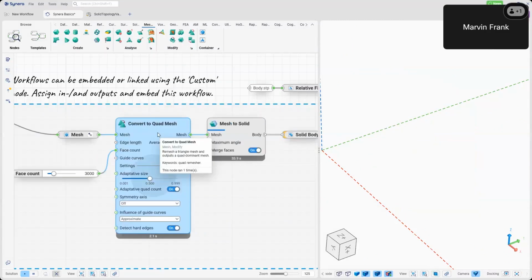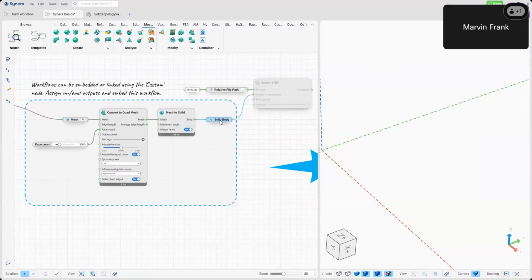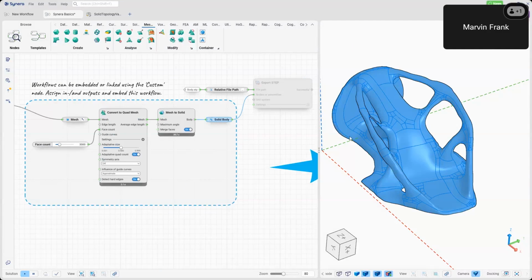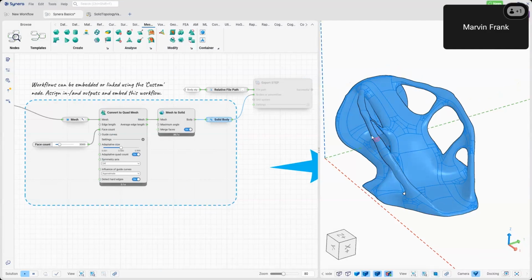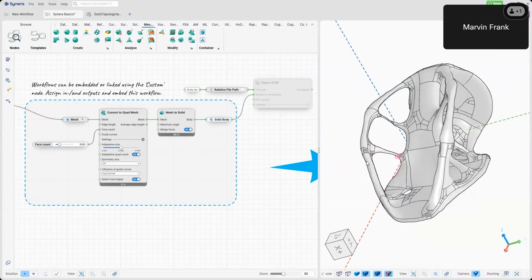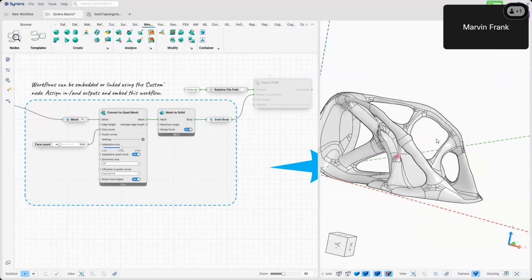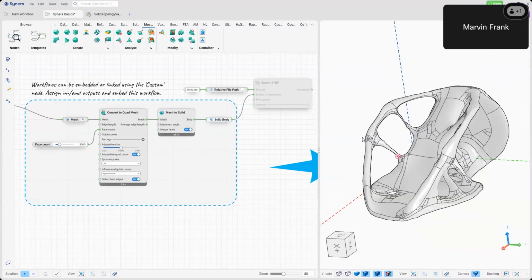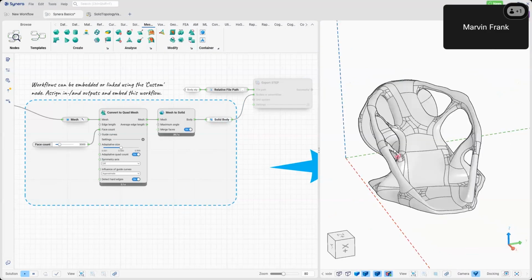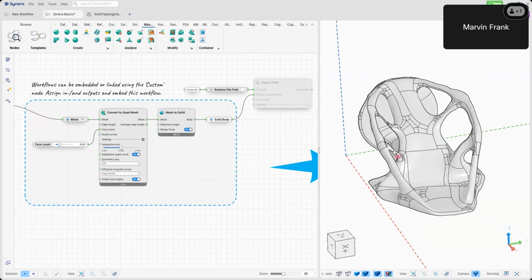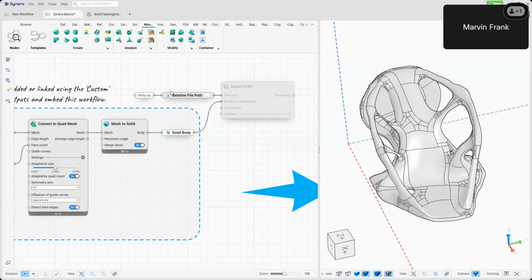So when this is run through, right now it has. That's good. So we feed that here again in this basic container. That's the automatic reconstruction of that mesh that we had before as a step file, can be IGES or whatever. In this case, I want to export it as a step, so I also provide a relative file path here within the file name, and then here I have the export step node that exports the step now to my location.